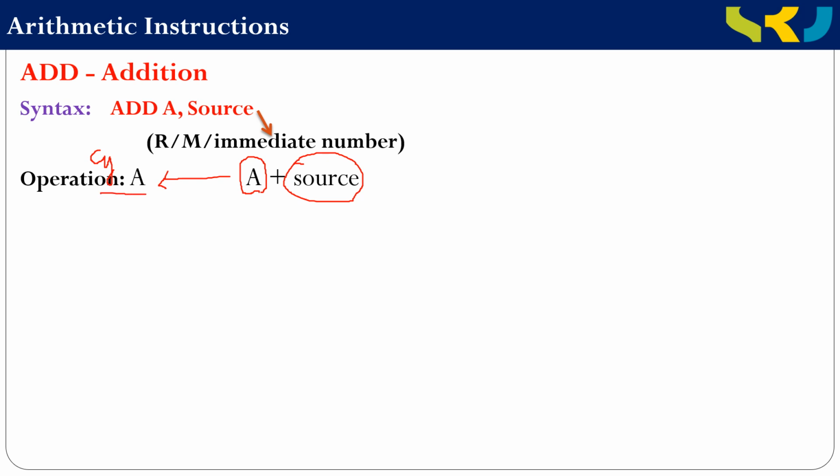When you perform addition of two 8-bit numbers, we get a 9-bit sum. But the accumulator alone acts as a destination, so to store the 9th bit information, the carry flag is used, which is available within the PSW register of 8051 microcontroller.